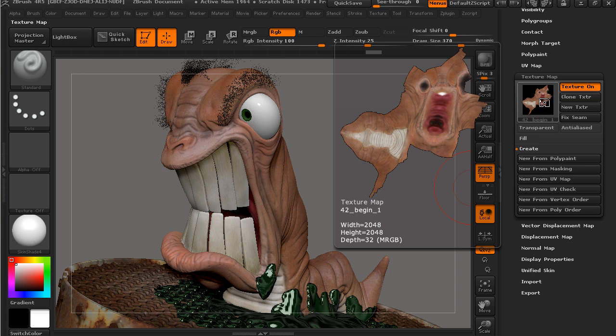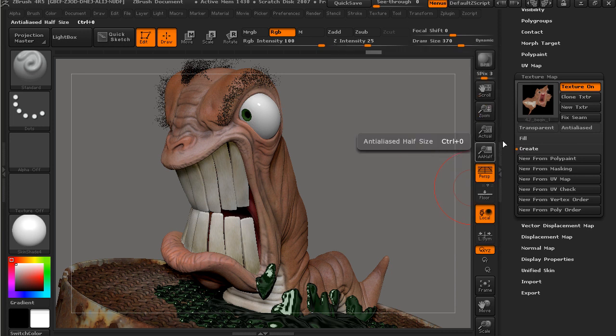And you can see that if I had to go in and make some adjustments to that, it makes a lot more sense as a user than a UV layout that's all broken apart like that. Now if you're not going to make any changes and you just need to apply it really quickly, then those UV layouts can work. But I just wanted to show you the different ways that you can create UVs. And now from this point you could export your maps, create those maps and export them out so that you can then reapply them to the UVs to your model here.